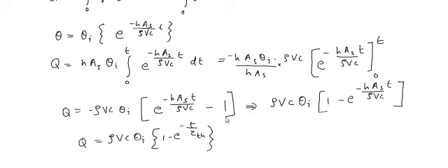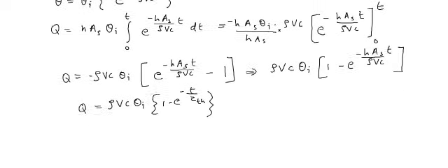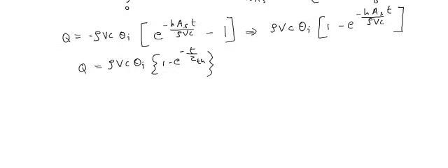Okay, so this is the rate of heat transfer as far as the lumped capacitance method is concerned. Now going back to the other one, let us see what is the importance of Biot number. So we have seen that Biot number is equal to h L_c over k, where L_c is the characteristic length. Now what is this characteristic length in the case of a plane wall? In the case of a plane wall, the characteristic length is the L itself. It's the length itself.